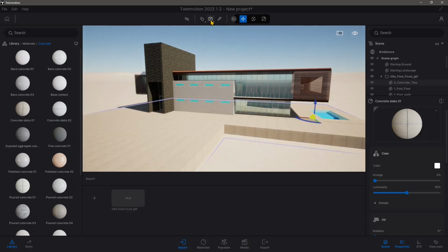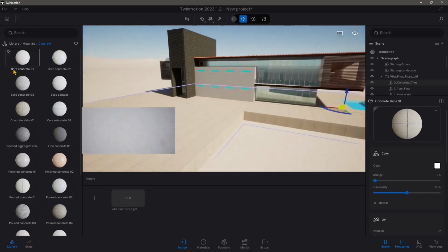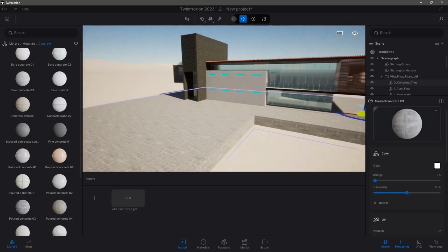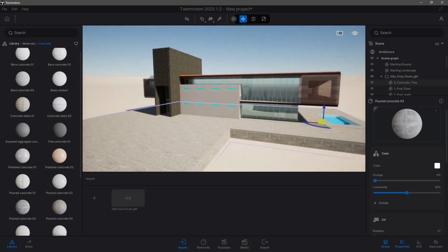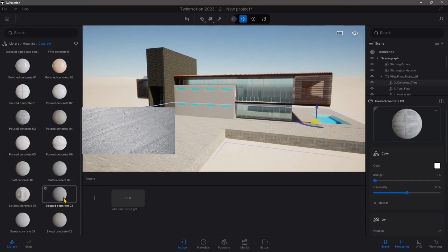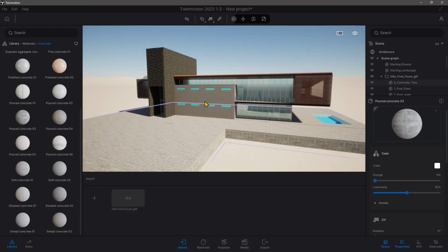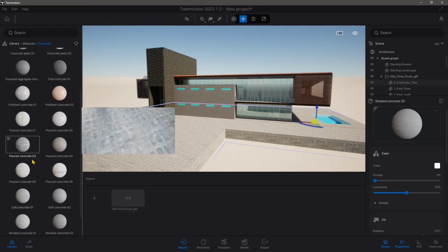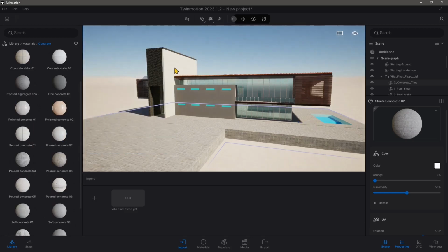Now it works. Sometimes you need to switch to cubic and then back to the object UV, and then it's going to work. Other times it doesn't, so usually this will be adjusted automatically, and now you can see it works. Now everything is perfectly mapped, so I can use my UV map or I can use my box mapping, and I can also drag and drop other materials real quick to other parts of the scene.